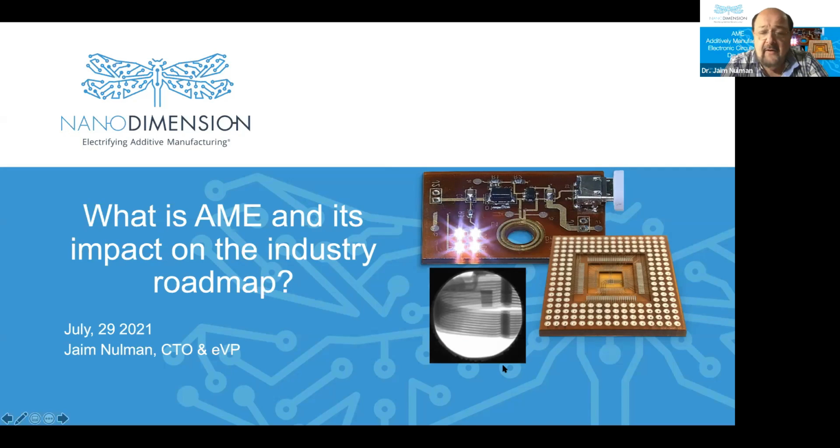Okay, so in the process today, the nanoparticles are sintered to about 25 to 30% conductivity relative to bulk, and we are developing a methodology and inks that will allow us to go to much higher values, and we consider 60% to be at least the minimum that we'll eventually need to get to. But that's a material which is under development right now.